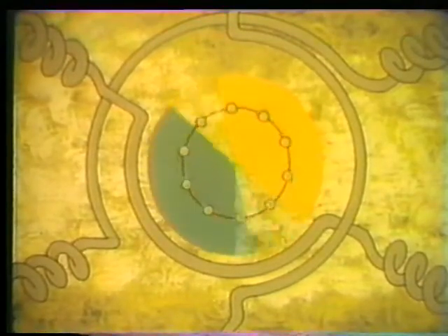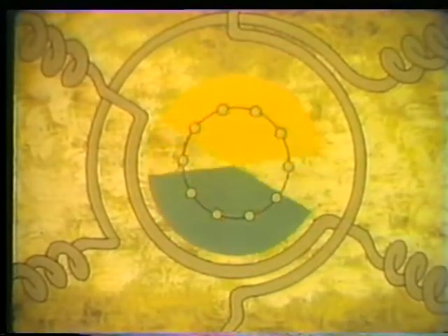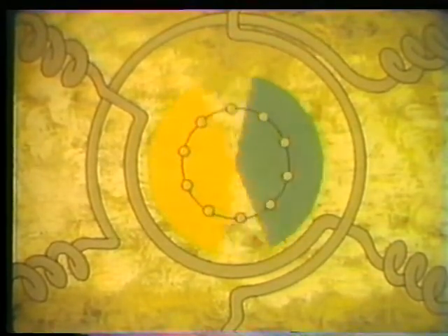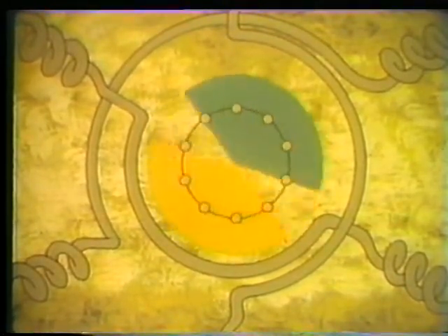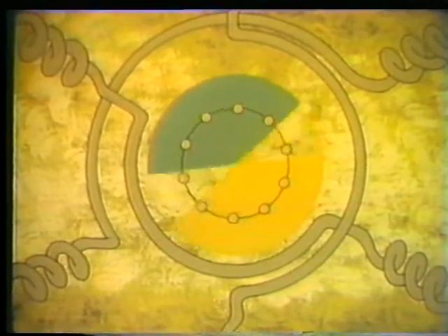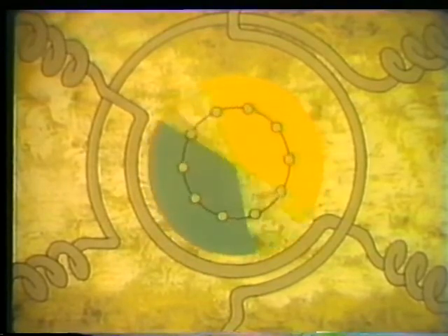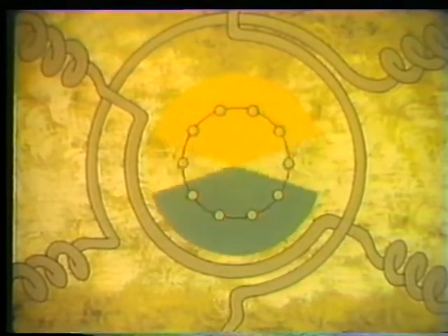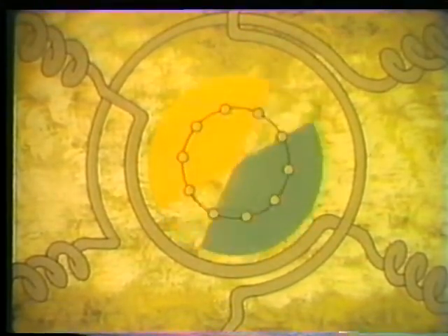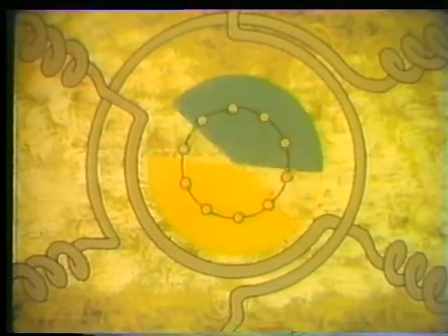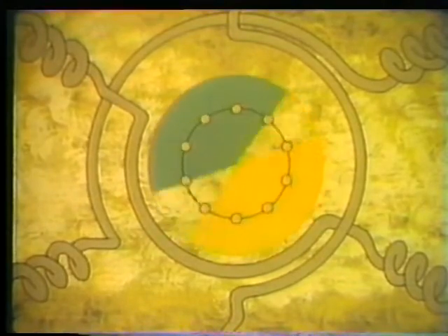In other words, the rotor slows down. Because of this slowing down, there is more relative motion between the stator field and the rotor, so slip increases. More voltage is then induced in the rotor bars. More voltage means more current flows, and the magnetic field of the rotor gets stronger. The rotor now turns more strongly, and the motor produces more power.